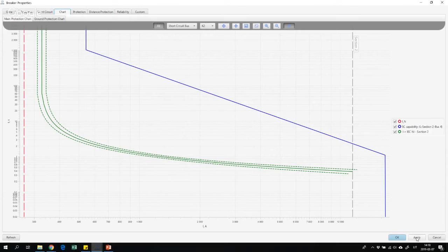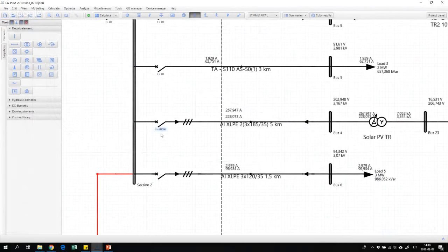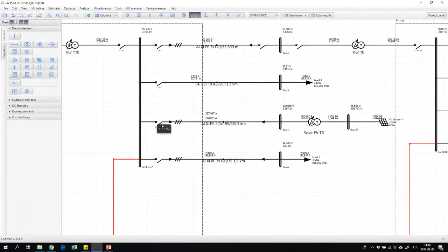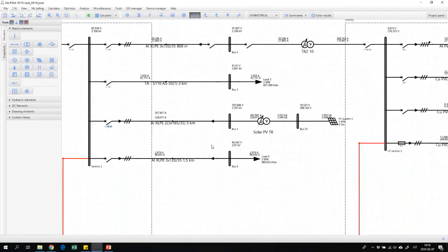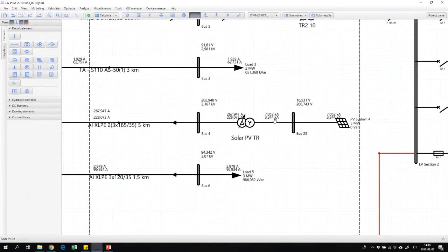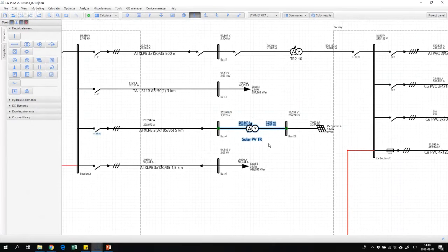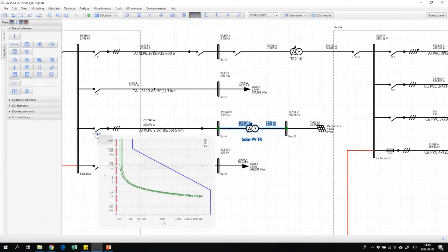So now we are working with protection in our substation panel. However, if it's, for example, an industrial consumer, the industrial consumer will have a fuse or a breaker which protects their network and their loads. So our overcurrent protection device setting should be capable to work selectively with that particular protection device in the industry, in the factory, or in the solar power plant network, for example.